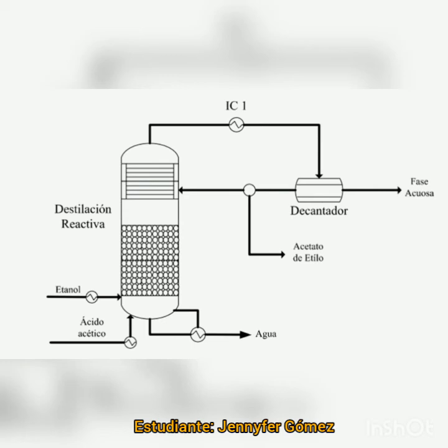The aqueous phase leaves the system, while the phase containing the product is divided into two flows. One enters the tower and consists of recycling to the distillation system, and the other is the product stream obtained as such. After this step, ethyl acetate is obtained with a purity of normally 96 mole percent.